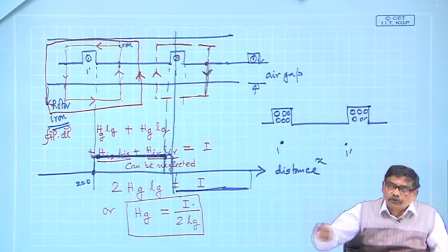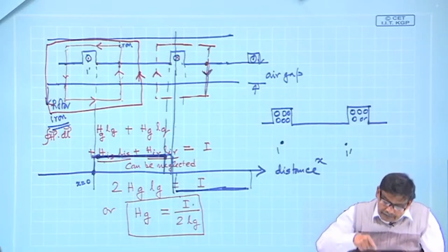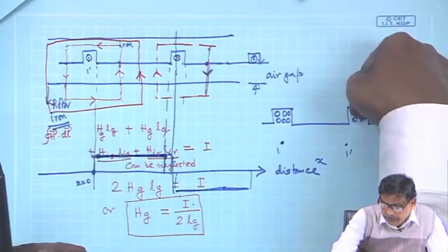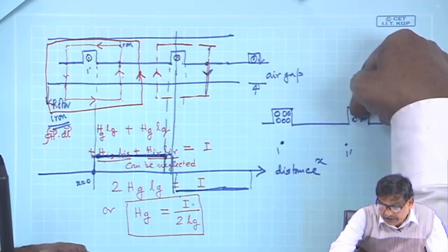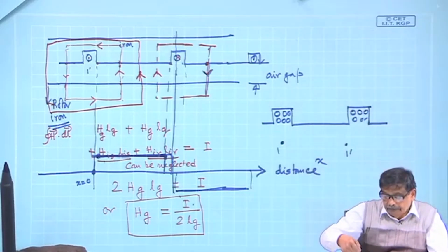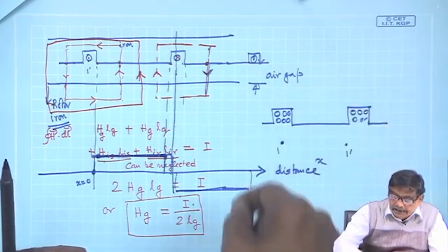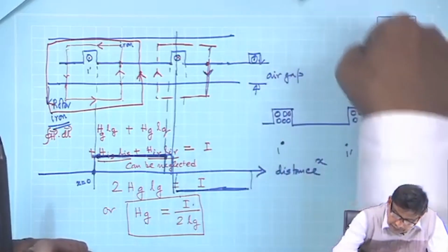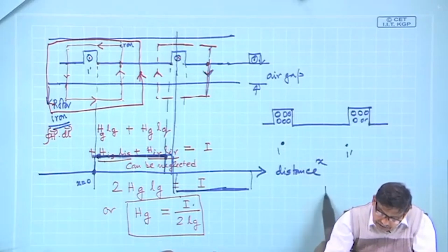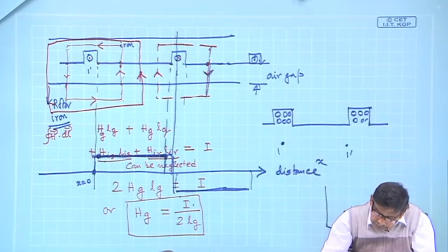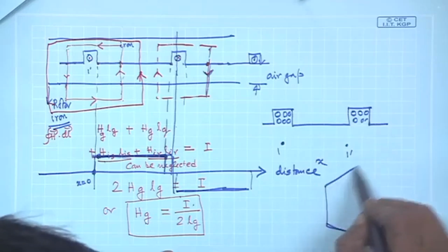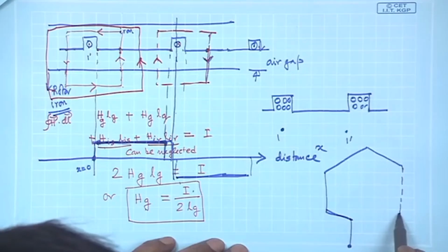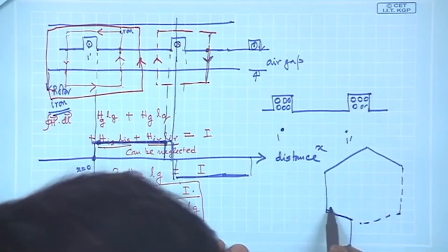You take a long piece of wire, one wire only, you push it in, at the back you go, then draw it through this designated return slot of that coil, and then repeat this once again, do not stop here, once again push it in, at the back come. So, it looks like this, go there, come out through this slot, once again come here, bring it back.